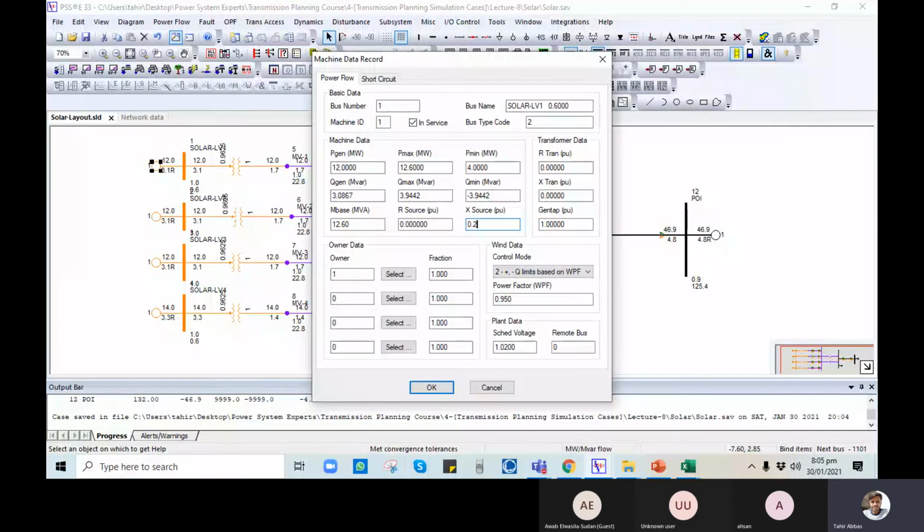Now different combinations can be generated based on the data available. This was the 1.5 megawatt turbine data. Now you can have a 2 megawatt wind turbine. It means that you have 25 turbines total, with 7 turbines in one collector group, another 7, and so on.